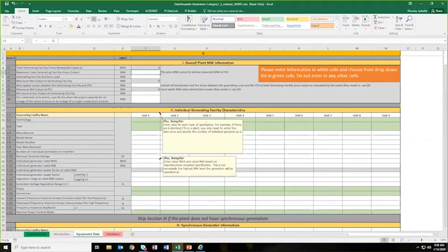It should be at your operating power factor. So it depends: if it's an old solar PV plant in SCE or San Diego area, they are required to operate at unity power factor, then yeah, use the unity power factor. But for single generators, you don't operate at unity power factor, so don't use the unity power factor.